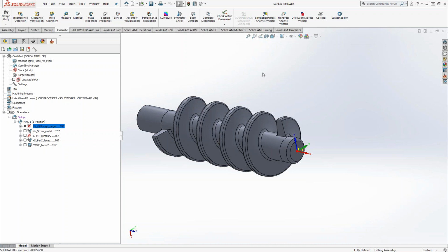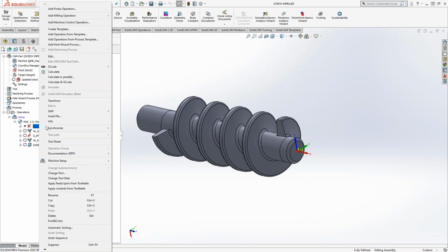If you're going to do any kind of 2.5D toolpath, 3D toolpath like I'm about to do here, or a wrapped toolpath, the Z still needs to point in the direction you want the tool to come from. In the case of a wrapped or a C-axis wrapped toolpath, the tool needs to at least come from a starting point before the whole part gets indexed. So the Z-axis is your tool axis, no matter what you're doing. Okay, so we've got this guy here. Let's see how long this takes to calculate.